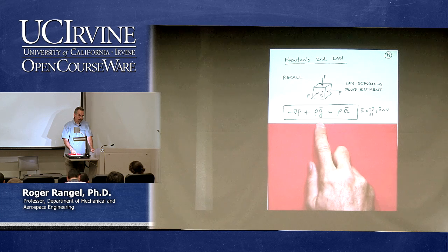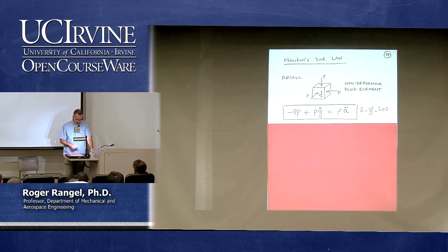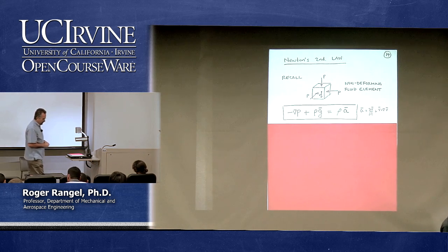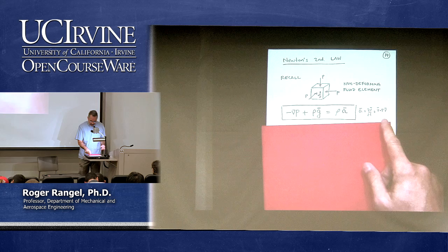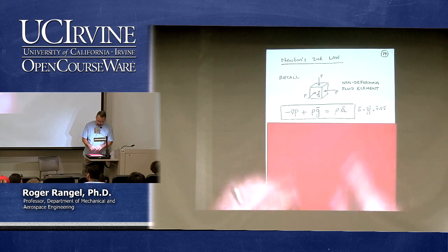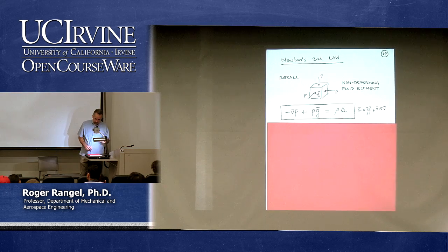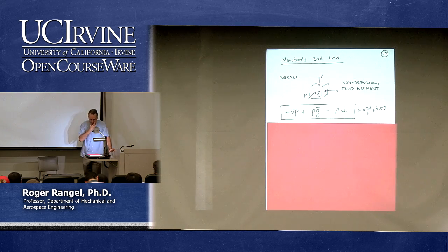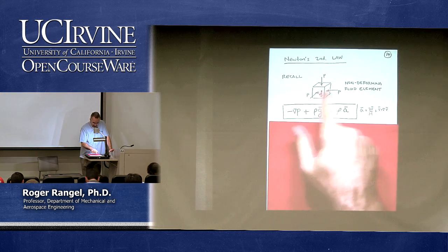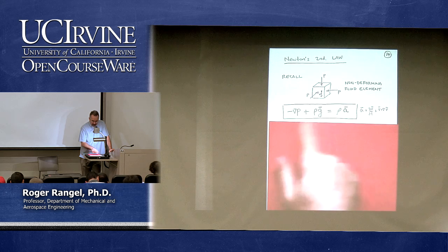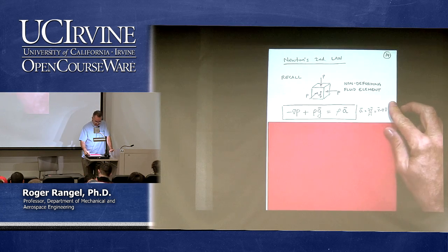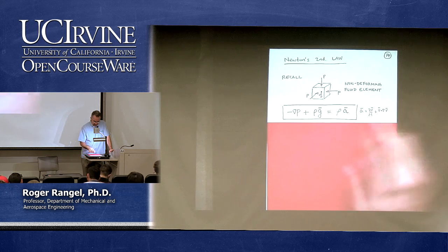The equation is per unit volume. Then there's the weight of the fluid element per unit volume, and the rho A, the MA term in Newton's second law, but divided by the volume. And I just put it here in little, even though we know what the acceleration means, right? Acceleration has those components, the local and the convective acceleration. And that was our element that we were looking at when we derived this equation. This goes back to the second week, maybe even the first week.